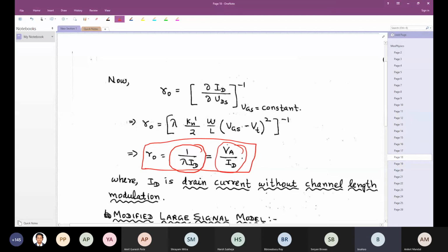So that we can have a unified model for the BJT and a MOSFET. In this course, as I said, we'll be discussing amplifiers. After we finish the MOSFET physics and the bipolar physics, we won't do an analysis of a BJT amplifier and then a MOSFET amplifier. We will do analysis of both of them together, because from a circuit perspective, the terminal characteristics can be abstracted into circuit parameters, and they both look almost identical.